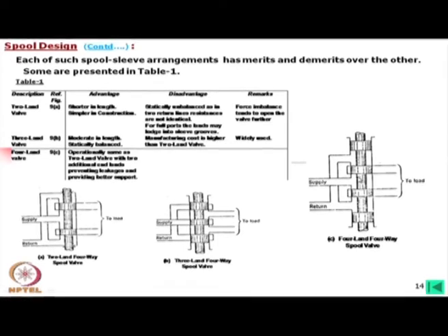So, this unbalance will be there, but as there is a land support, there is no chance it will go into the groove, and also the leakage will be less. In that case, this is directly open to the outside, and the leakage has to depend only on this seal. In that case, this path and then sealing. Okay.